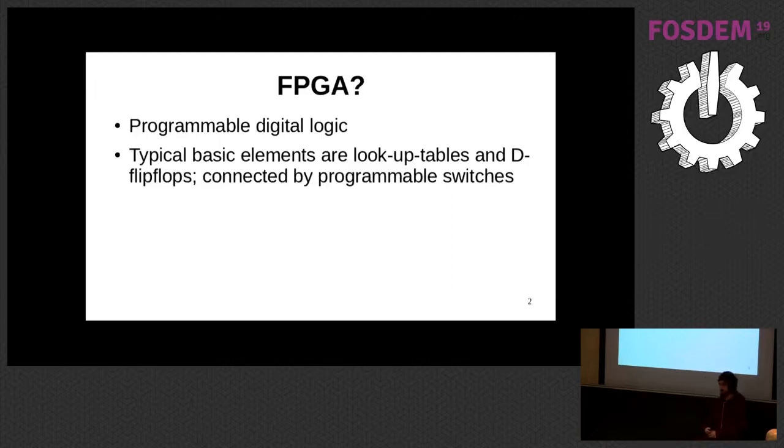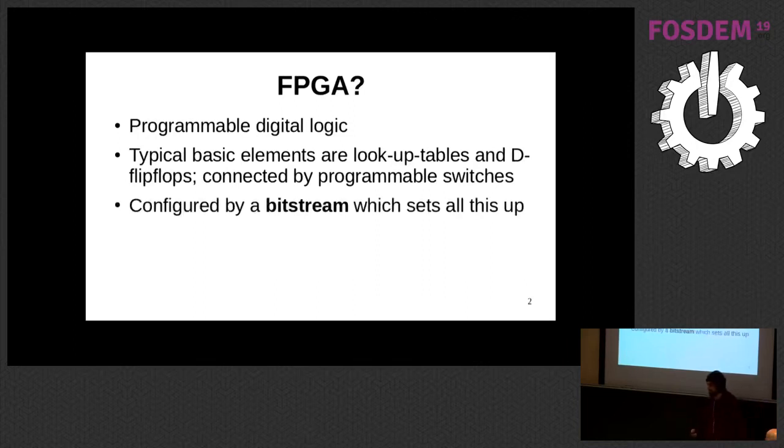So effectively you have a big device full of programmable logic that you can build any logic circuit you want on. It's a much cheaper way to do your own logic than taping out your own ASIC, while being a lot neater than putting a load of logic chips on a breadboard. This is all configured by something that we call a bitstream. It is literally that, a load of bits that set up all this functionality, set up all the wiring, fill the lookup tables, et cetera.